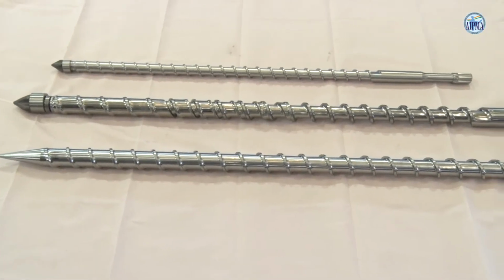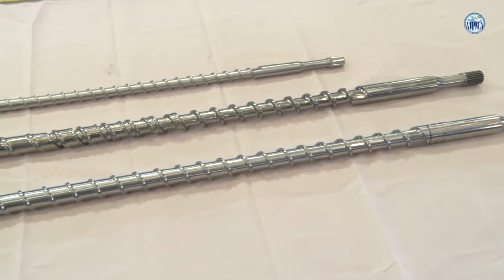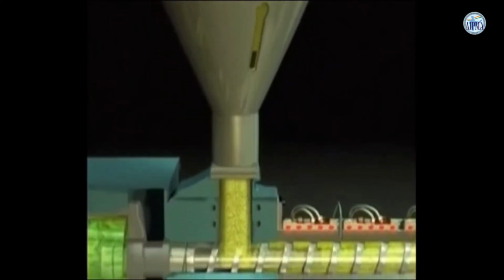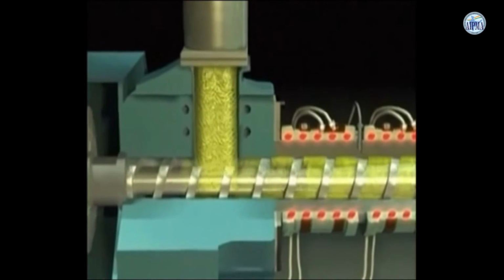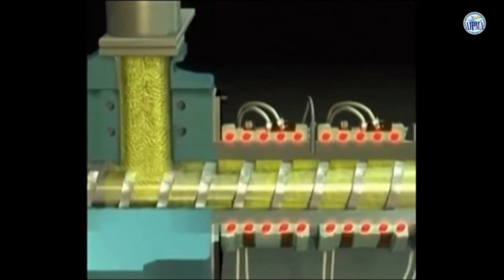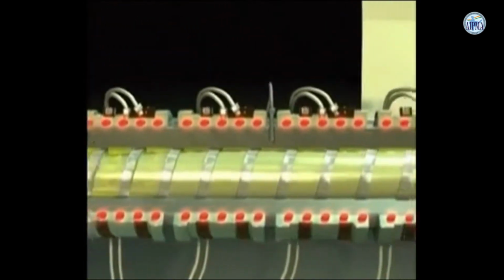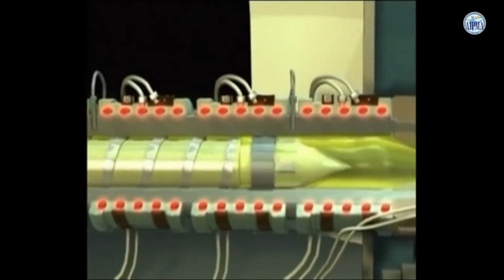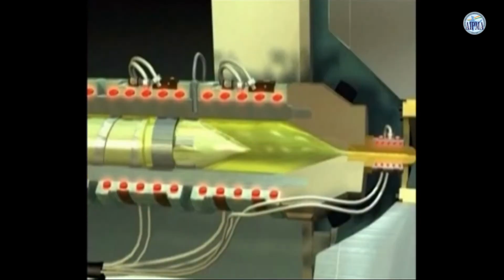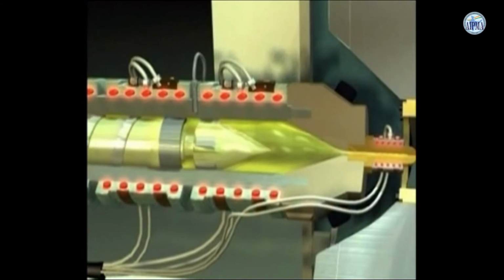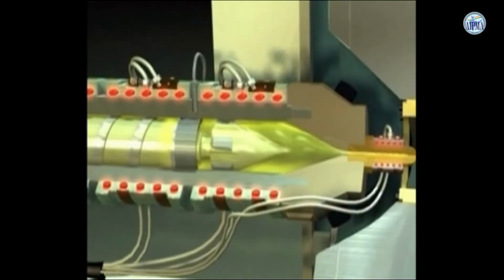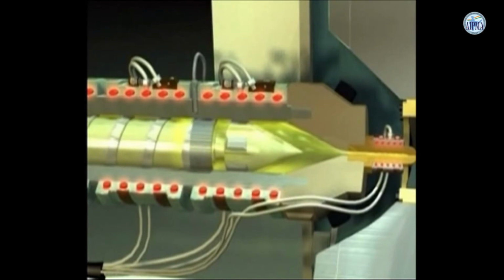Feed screw. Screw performs the following two functions. Plasticizing. The injection feed screw rotates through driving motor and screw geometry. It helps to melt material from the hopper down into the front of the barrel. Melted material moves forward by conveying action of screw flights. After desired volume is accumulated in the barrel, screw stops.